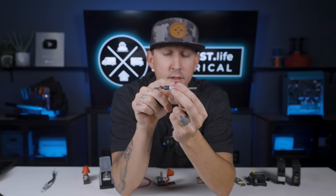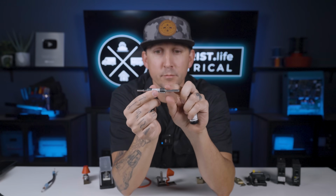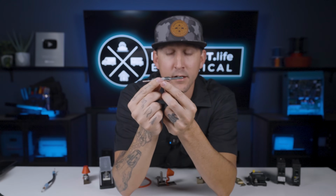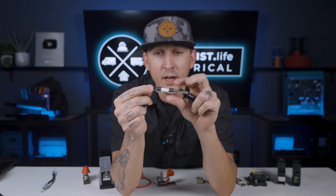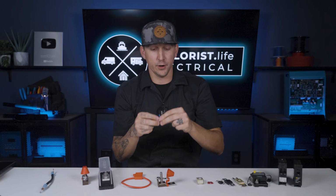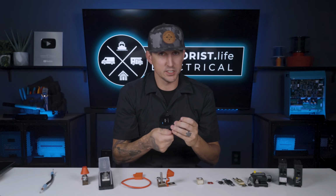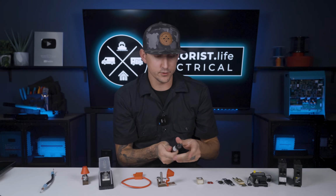Power comes in, there's a filament on the inside of this that melts in the case of an overcurrent event, and power goes out here. You've got that hole on the inside, and this is what your PV connectors are actually attaching to. And these are great. They're waterproof, they're weather resistant, they can be installed out in the elements, just the same as your PV connectors, because that's what it's designed for, and it's great for that.